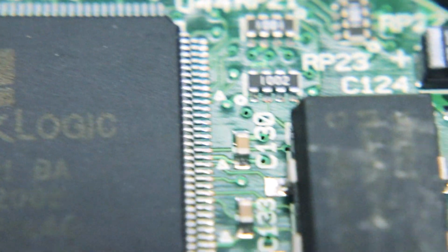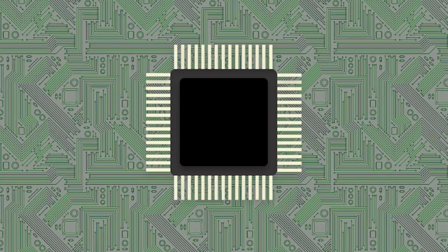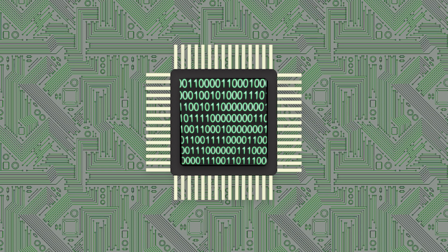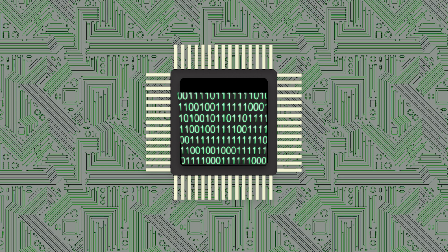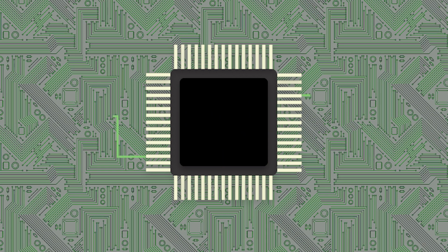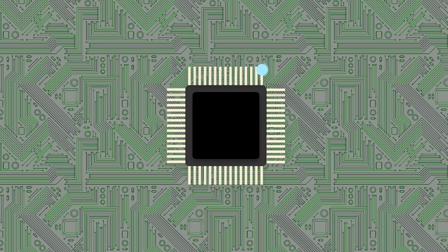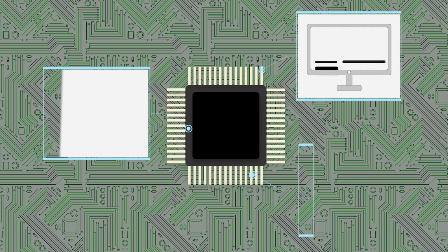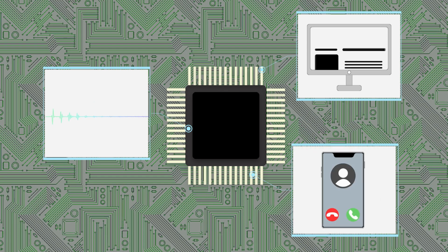What kind of chips do electronic devices use? There are two different types, analog and digital. Digital chips are built to store and process information represented by binary digits, and only deal with discrete variables. They use digital circuits that operate on two states, either on or off, representing the binary digits 1 and 0. They are commonly used in computers, digital signal processing, and telecommunications. These chips are more expensive to buy and have quicker product cycles.